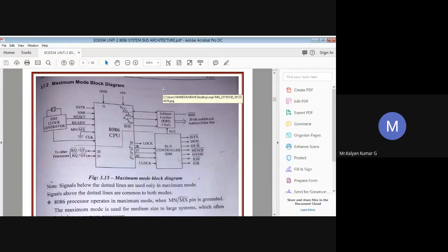Normally, the bus controller can be configured for uniprocessor mode of operation by simply grounding the AEN bar signal and IOB, and applying plus 5 volt to CEN.